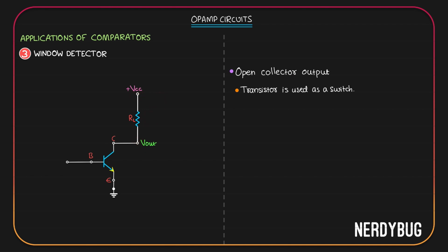I said the transistor is being used as a switch. The idea is very simple. We will get some input at the base of the transistor. We know for IC to flow, VBE should be greater than 0.7 volt. So when we have enough potential at the base, the transistor will be switched on and collector current will flow like this. If it is not enough, there will be no collector current. Let us mark the collector current.